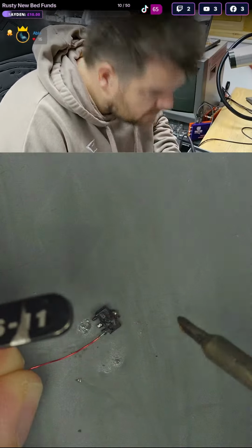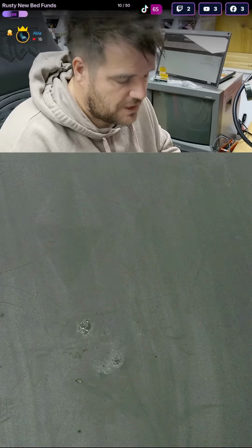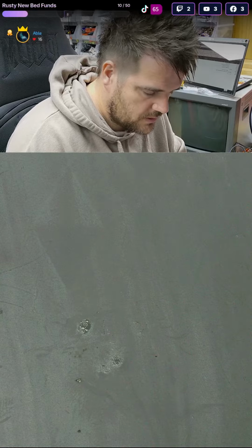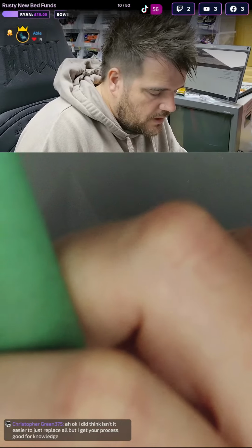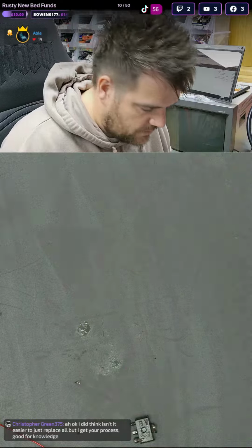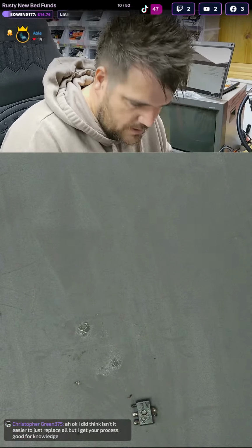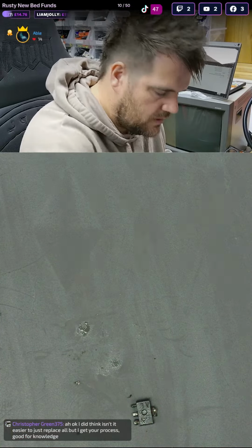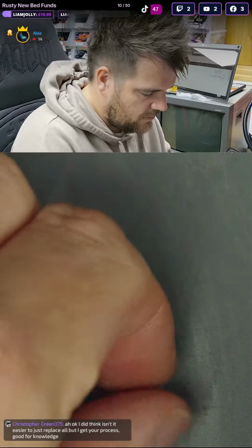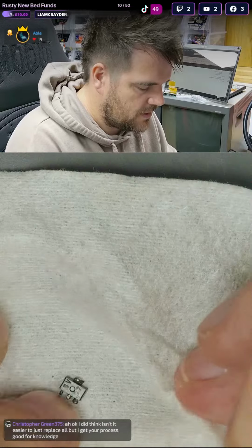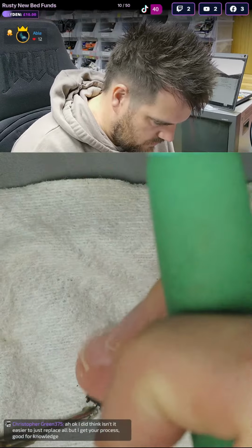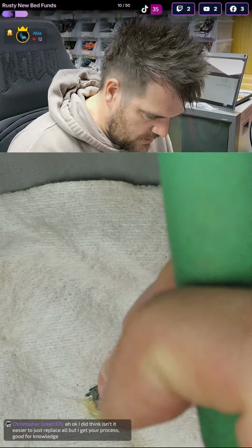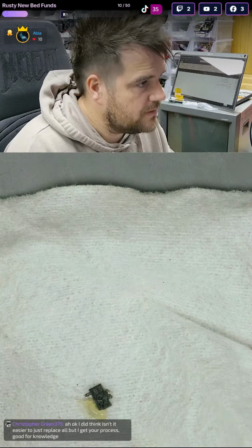So this is going to take me probably 30 times longer than just doing it without measuring all the components, but in the long run, the next board I have to do for a customer is going to have all these components already soldered on from the factory, and this does not want to take solder because it's dirty. That's the other downside, because it's got that corrosion on. It doesn't even want to attach the wires to it very well.